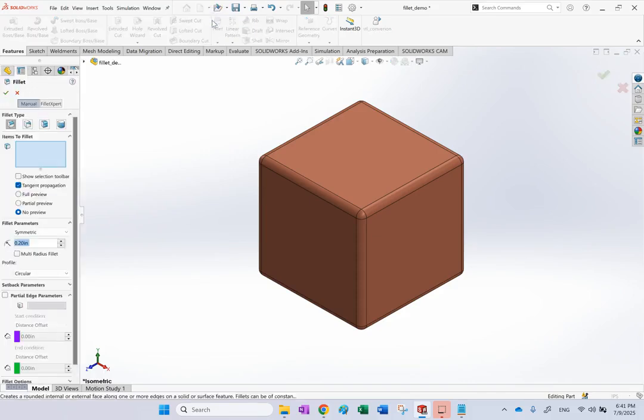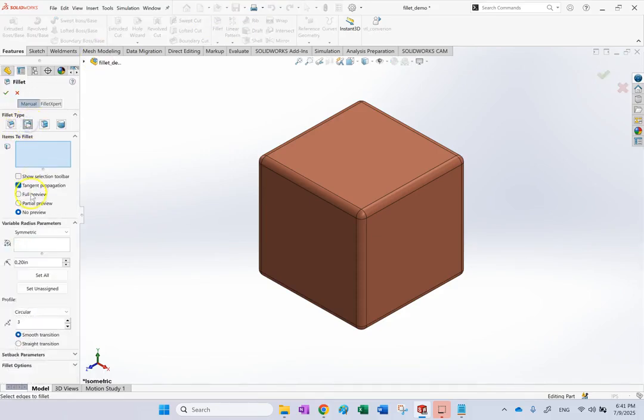Once you go to fillet, you can use this option, and here you're going to get a bunch of points along which you can provide different radii, and then it changes linearly from one to the other. But clearly in this case, it is not going to be really a nice transition, okay? Most of the time that transition is a linear transition from one radius to the next. And I tried that. It does not give you such a look.